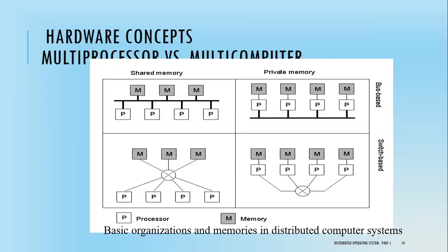A bus-based multiprocessor consists of some number of CPUs all connected to a common bus, along with a memory module. A simple configuration is to have a high-speed backplane or motherboard into which CPU and memory cards can be inserted. A typical bus has 32 or 64 address lines, 32 or 64 data lines, and perhaps 32 or more control lines, all of which operate in parallel.